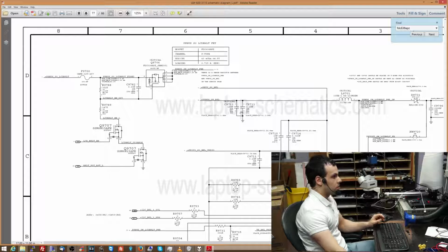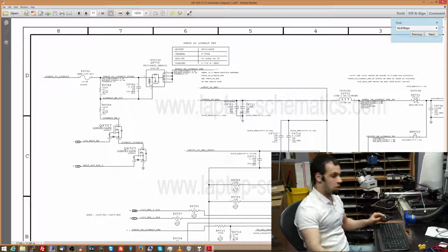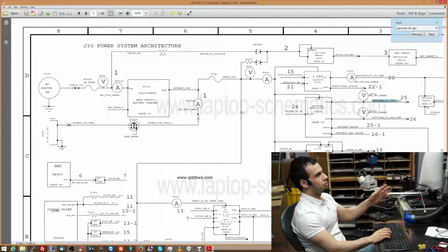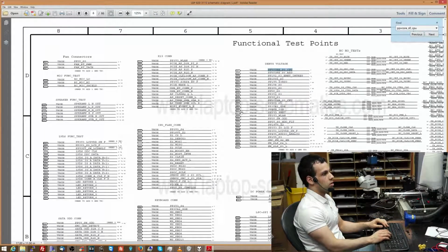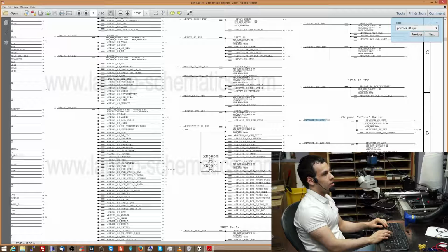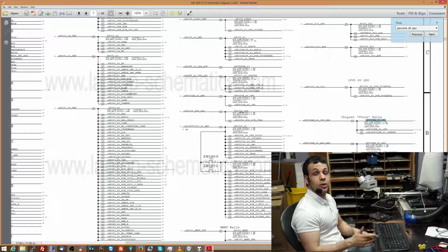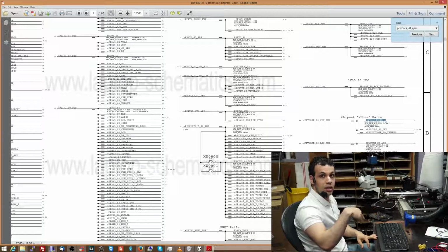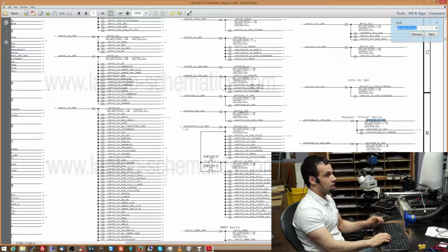There are other interesting uses of a transistor as well. So what I mentioned in the inductor video before was how there was a buck converter that was being used for CPU power. So what I was showing you is how you can turn a bunch of pulses into smooth power by using an inductor and a capacitor. So the inductor is only going to pass the DC, and the capacitor, which is going to ground, is only going to pass the AC, and it's also going to retain some charge.